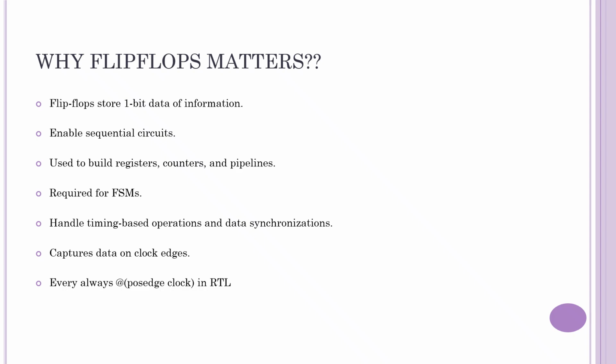Third, they build registers, counters, and pipelines. Let's break it down. A register is just multiple flip-flops storing multi-bit data. And a counter is flip-flops changing state with every clock cycle. Processor pipelining uses flip-flops to store intermediate stage results. Basically, if you are building any serious digital system, flip-flops are involved.